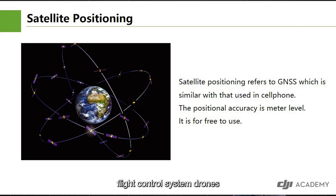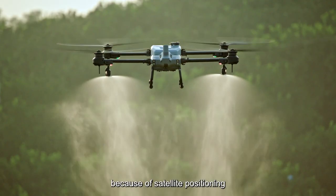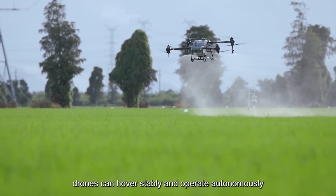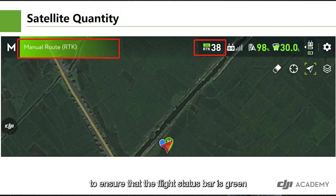Flight control system. Drones can fly stably along the established routes based on satellite positioning, that is, GNSS in the remote controller. Because of satellite positioning, drones can hover stably and operate autonomously. So remember to ensure that the flight status bar is green before each flight.